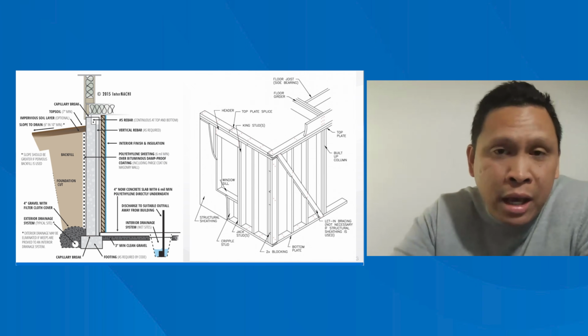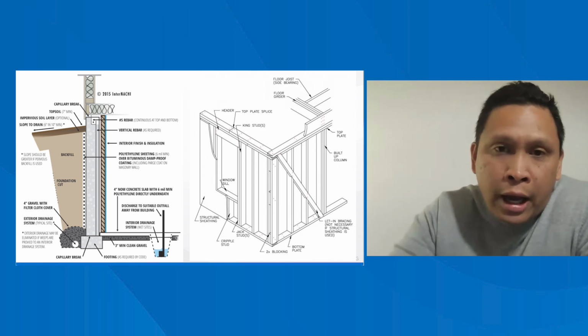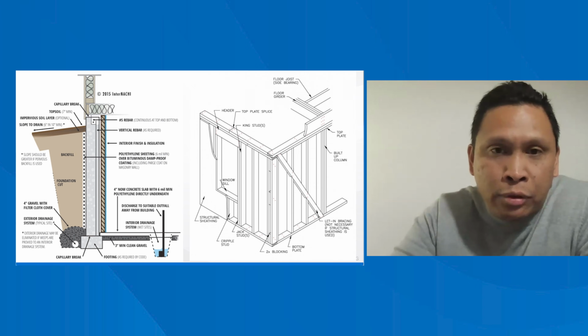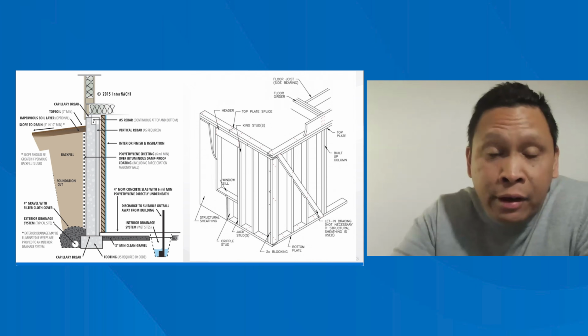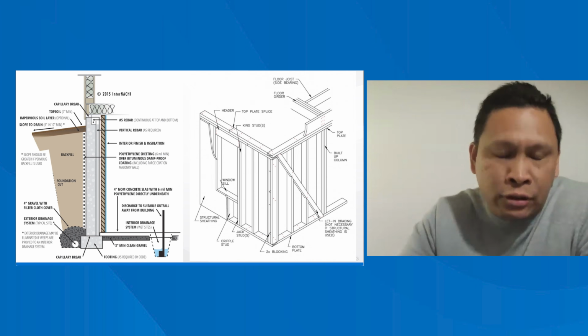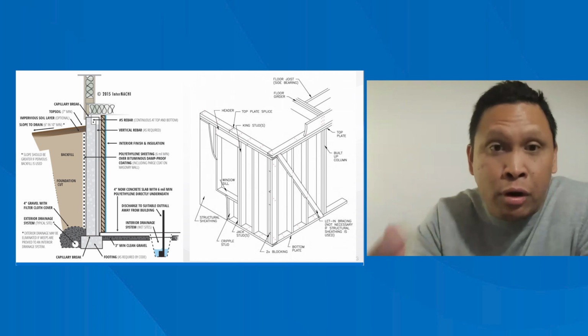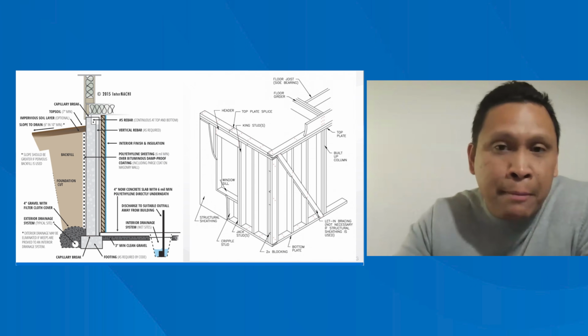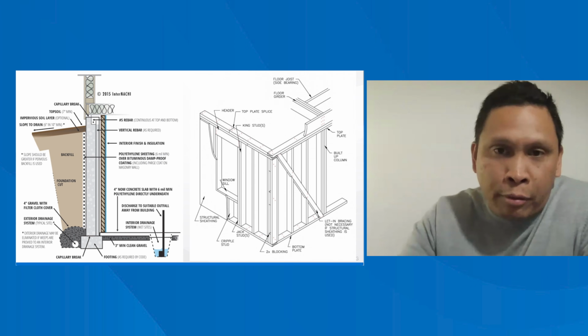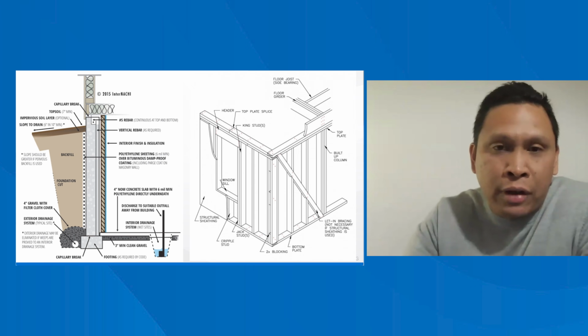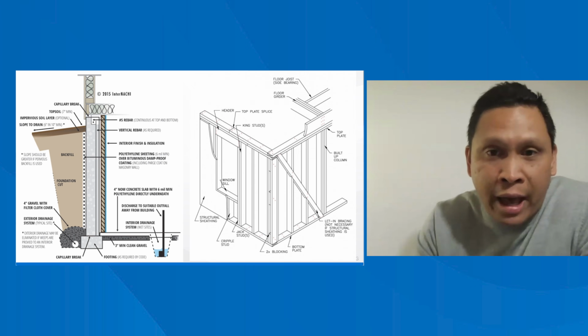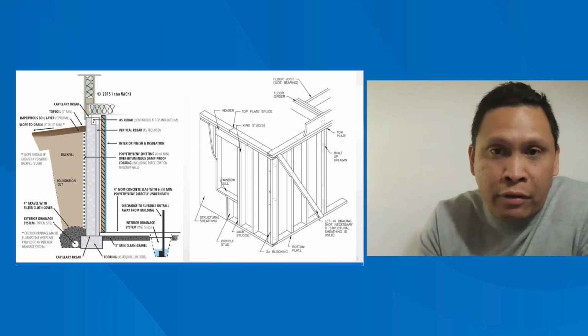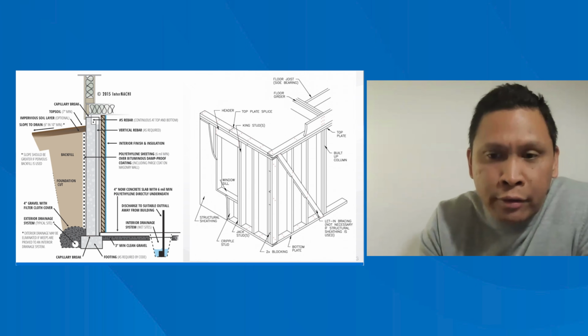Now, one of the other things that we would not be able to see at a resale, but that we might be able to see when we are helping a family build a home from scratch, is when they haven't backfilled the foundation. That's the act of actually putting the dirt back into place next to the foundation. Next is damp proofing. Nothing is ever going to be waterproof, but water resistant. That damp proofing is going to help make the concrete foundation as water resistant as possible.